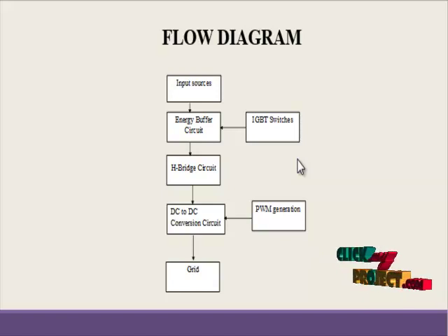Following the voltage command signal, the circuit has 4 switches, 4 diodes and buffer capacitors built into the buffering circuit. The capacitor holds the positive voltage of the process. The circuits, positively and negatively superposed, supply voltage and set the DC link voltage to 3 levels, depending on the state of the switches. The buffer capacitor changes the DC link current, and the conversion stage consists of 2 switches, 2 diodes and a chopper inductance for operation at a constant level.